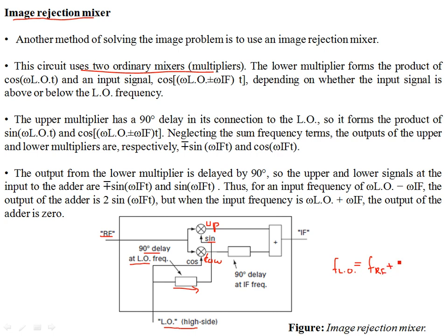Now FRF could be higher or lower than the intermediate frequency, but for a standard AM broadcast, this FIF is standardized at 455 kilohertz. Once you mix FRF with the local oscillator frequency, the difference is FIF, which goes inside the IF bandpass filter, and then to appropriate amplification before the detector.